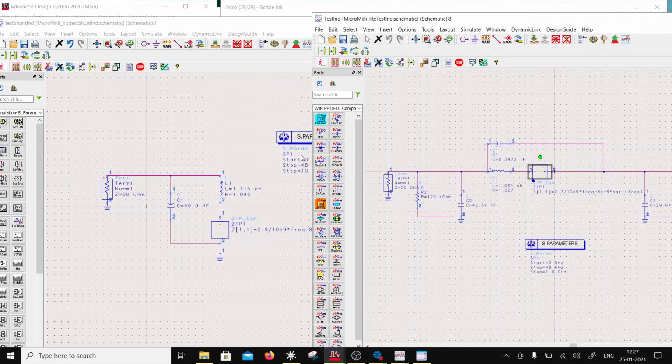As far as the MIM capacitor, it is going to follow the same set of equations, right? It's just that, instead of j omega L, now you are dealing with 1 over j omega C. So as a simple modification, if you try it, you will get it. So I don't want to do a MIM capacitor series and shunt. I will leave it to the audience to do their series and shunt capacitor modeling, right?